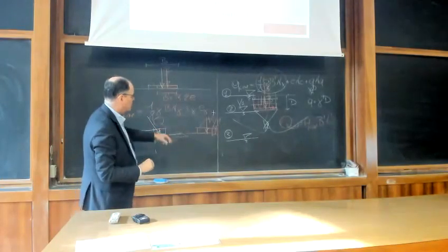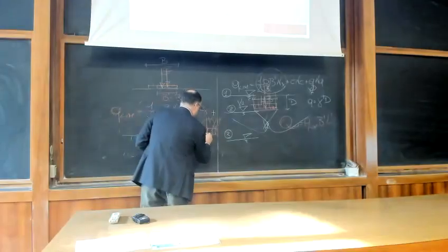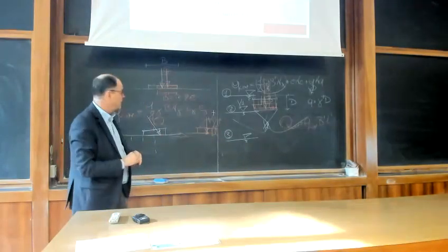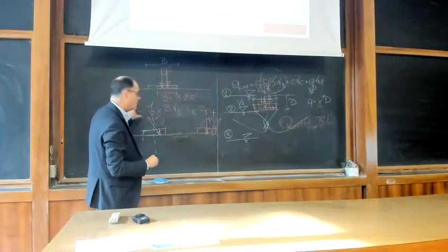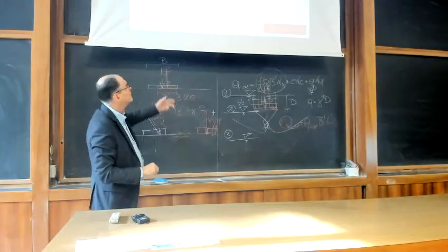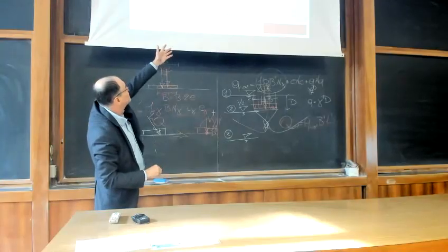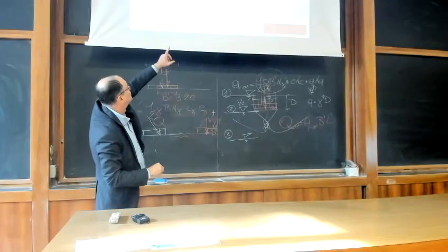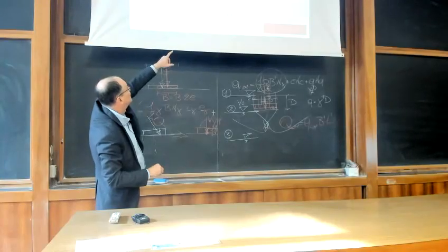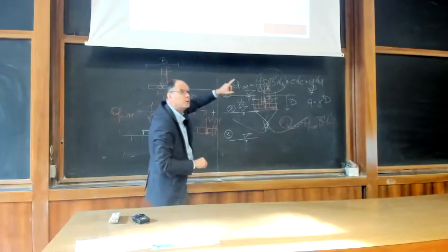You just consider that you have a footing subjected to 3 different loading components instead of a footing subjected to a resultant which is inclined and eccentric. And it is relatively easy to find the relationship between eccentricity, inclination angle alpha, and the 3 components.